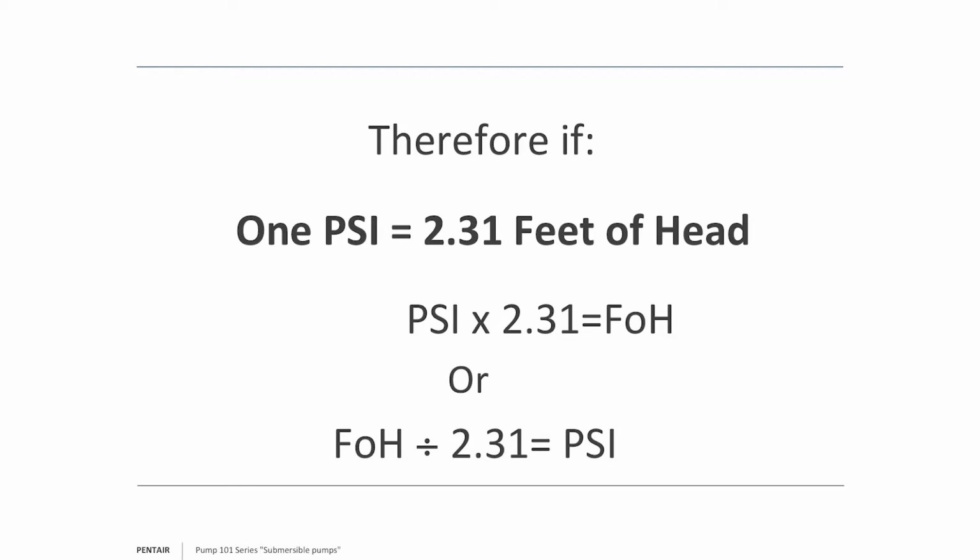This is important to remember, not just for the conversion of the pressure into feet of head, but if you're doing landscaping projects, landscapers, Hunter, Rainbird, all those charts, if you read closely, they report not in feet of head of friction loss, but in psi. If you do not make that conversion and you look at a pump chart that's based upon feet of head, understand you're going to be off by a factor of 2.31 and most likely will undersize your pump.